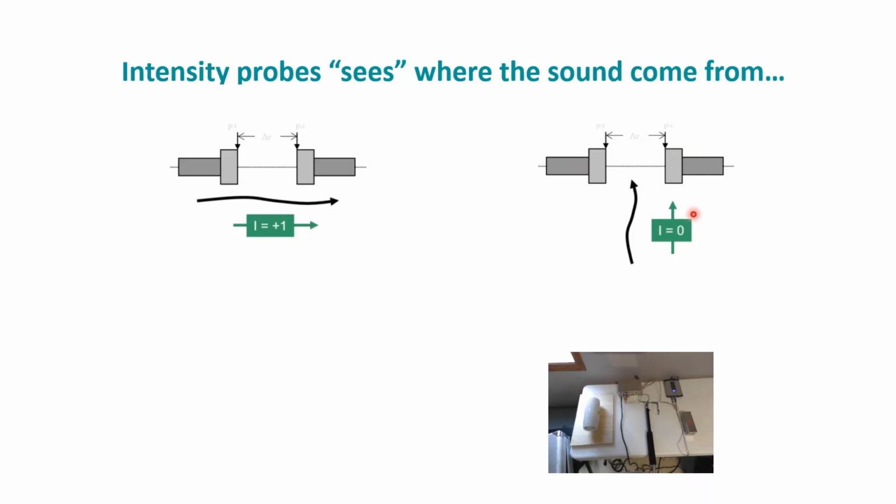So it's really important that you're holding the intensity probe, specifically this type of intensity probe, in the right direction of where sound is coming from. And a lot of the TestLab software will actually do live updates while you're doing it to make sure that you can scan and kind of get a good idea of the direction of the sound that you're catching